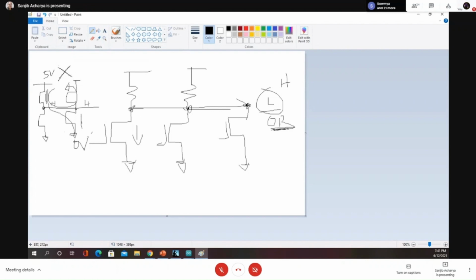So in order to keep your outputs connected together, as your friend mentioned, in the board reset you will have multiple sources of reset, right? Your reset might come from a push button, from a power supply, or from a supervisor circuit, a voltage supervisor chip.